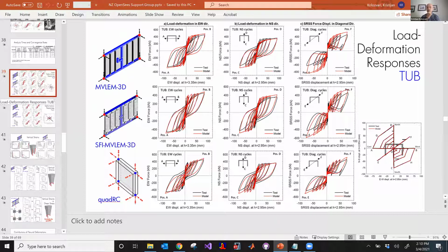For punching failure through the slab, I think you would have to use some kind of brick elements or something like that. Maybe there's some easier way to do it. It depends, there are many levels of modeling. If you want to make a really detailed finite element model, like Abaqus or something, then you would have to find maybe a cubic element with concrete. I'm not even sure that's available in OpenSees currently. But there are other simpler models with maybe more macroscopic elements too. Thank you so much. These elements are not for the through-thickness kind of failure.